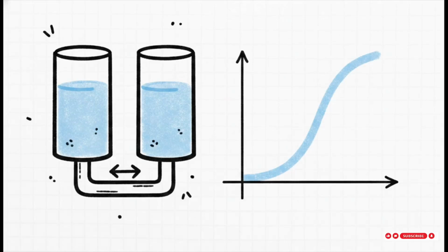Okay, so if you connect two interacting tanks, meaning the flow between them physically depends on the fluid levels in both tanks at the same time, they form a multi-capacity system. Because they interact with each other, they create a cross-product term in the denominator of our transfer function. This creates massive mathematical resistance that heavily slows down the response. As a result, interacting tanks will absolutely always give you an overdamped response. Because zeta is greater than 1, it's going to be very, very sluggish.